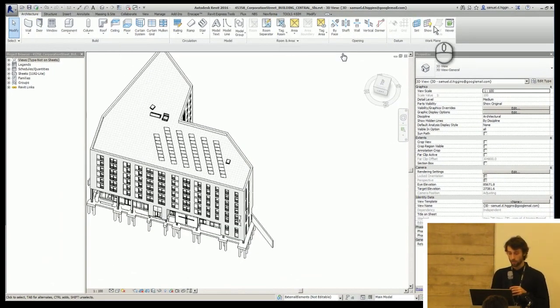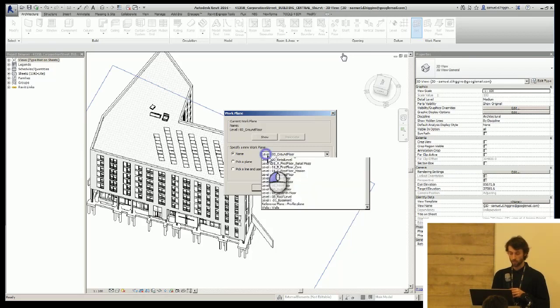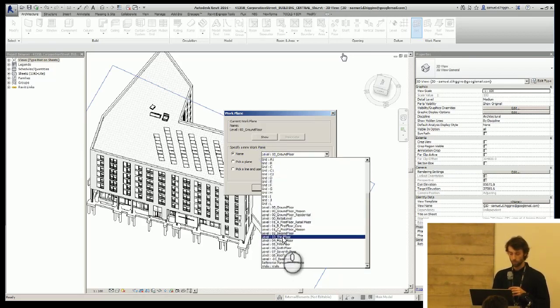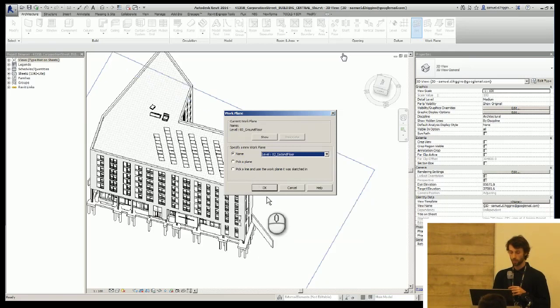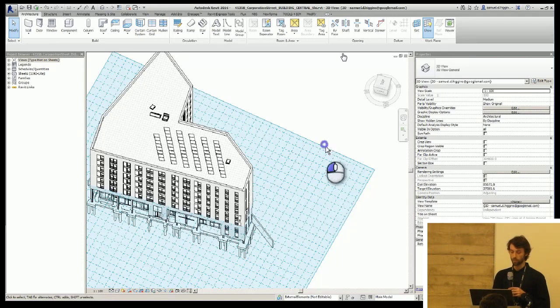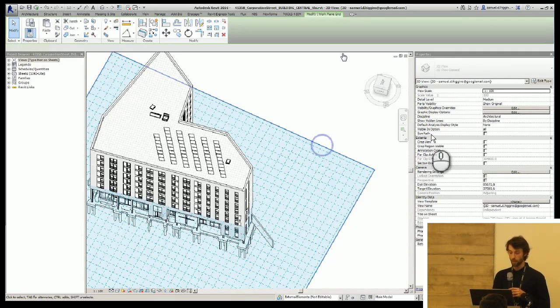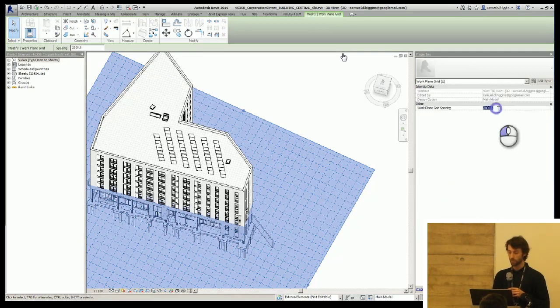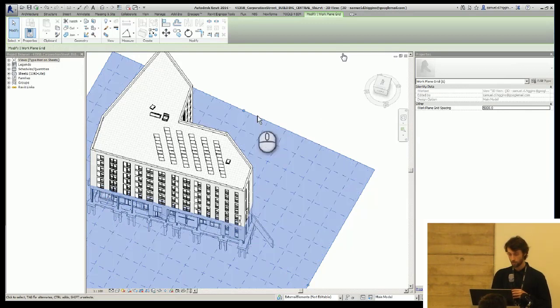If we go to Architecture, Set, specify this time a building level as the work plane, OK that, and go to the show function. You see that visualized. Now I don't know if you know, but the grid spacing on this is entirely malleable, so I don't like 2000. I typically like to work 1000 or 5 meters when I'm working in here. It can be used as a decent reference whenever you're sketching in 3 dimensions. So you can see it scale up to 5000 as required.